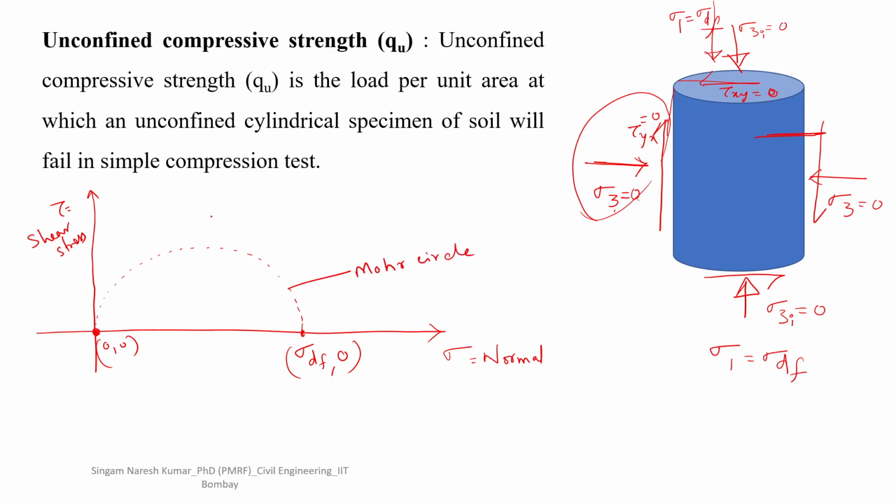Now this test is generally done on clayey soil. For pure clays, the friction angle is 0. Now, what is the concept of the failure plane? This is called the failure envelope.